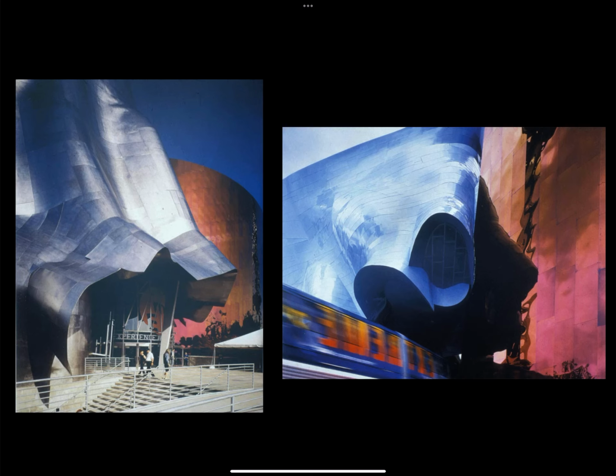The second strategy is to apply colored finishes to metals. So the blue volume that you see is an enamel-coated steel, and the iridescent volumes are steel that has been dipped in an acid interference bath. The interference interferes with certain wavelengths of light and allows other wavelengths of light to come through, and that's what gives the metal its iridescent quality.